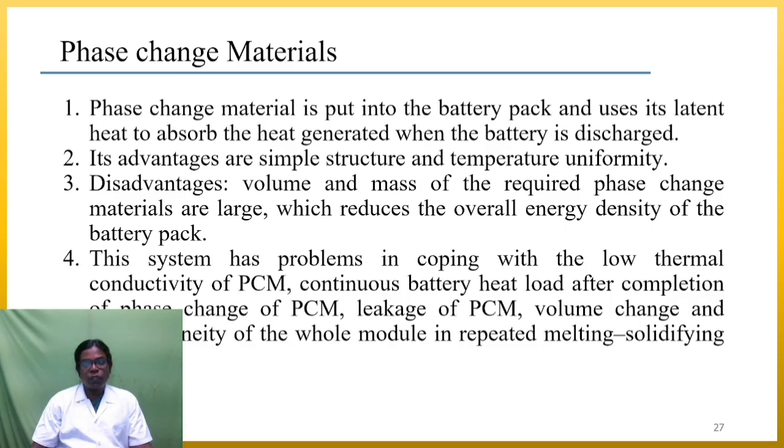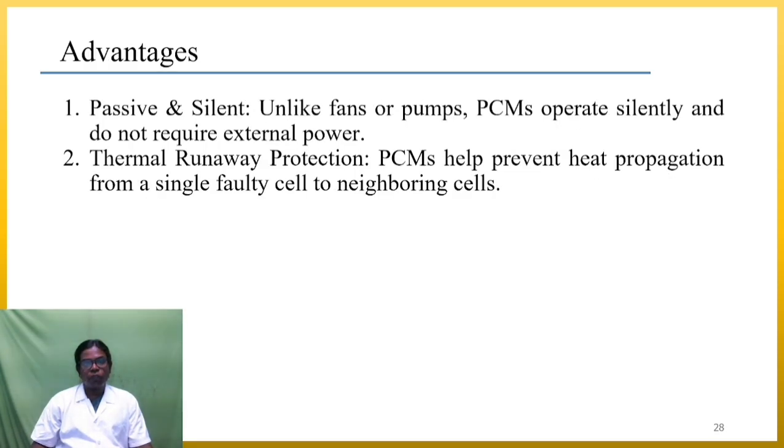Other issues are the continuous battery heat load after the PCM is fully melted, leakage of PCM, volume change, and inhomogeneity of the whole module over the repeated melting and solidifying process. Advantages: passive and silent. Unlike fans or pumps, PCM operates silently and does not require external power. Thermal runaway protection: PCM helps prevent heat propagation from a single faulty cell to neighboring cells.